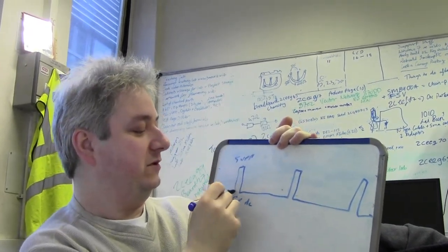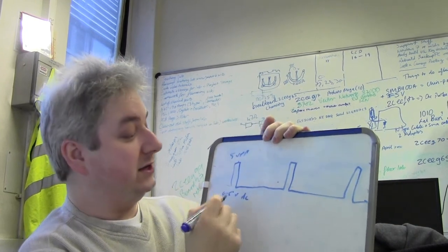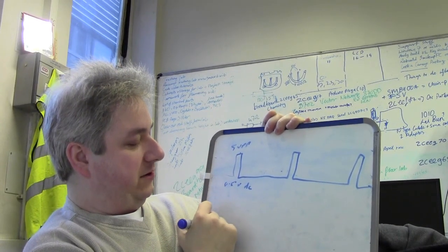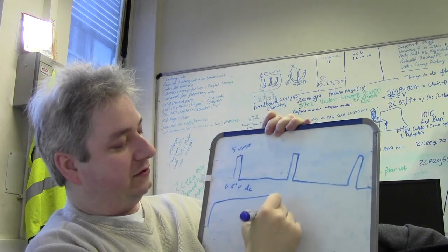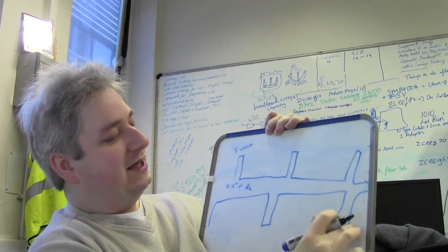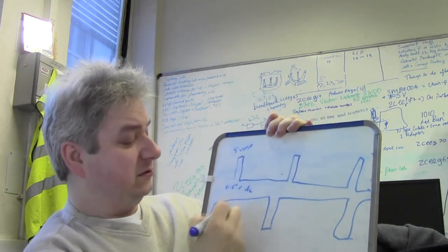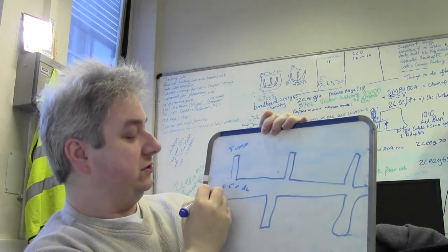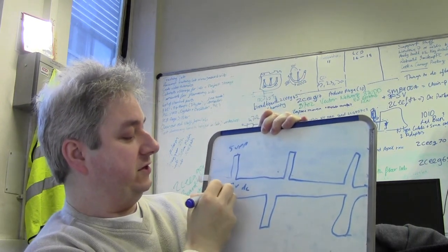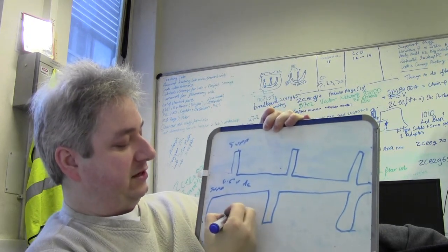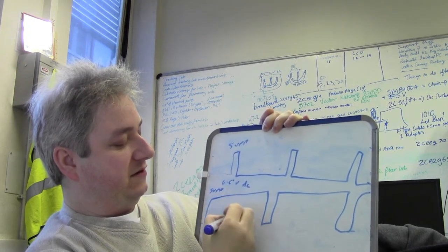I'm not going to go into the maths because this is just a quickie. And you've got another scenario where your pulses are on for a very long period of time and only off for a very short period of time. This is going to be almost maximum voltage, so you're almost permanently on at 5 volts peak to peak. So this will probably average out to about 4.5 volts, maybe 4.8.